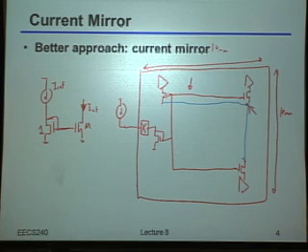Now, what's the problem with that wire? You said a second ago there shouldn't be any current flowing through that red wire. How about through the ground wire? Is there any current flowing there? Yeah, there's a lot of current, right? Because I just said the whole chip can have amps of current through it. Well, guess what? That wire can have resistance in it, right? And if I've got some current, for example, from some other circuit flowing through here, guess what? You will get a voltage drop between the quote-unquote ground on the two sides of the chip.